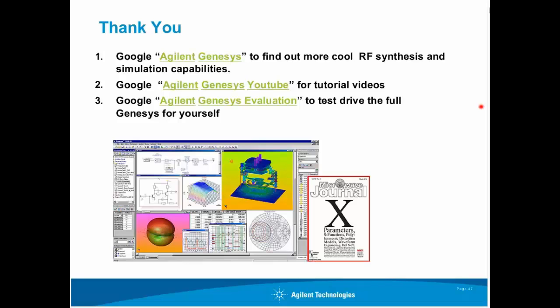You would complete your synthesis of your filter and the system capability, and then you can export that to ADS. We have export capability, and it pulls it over, including the analysis, which turns into a test bench in ADS and displays it in ADS. And so then you can use all the capability in ADS on your filter.